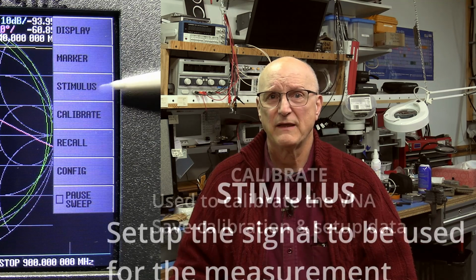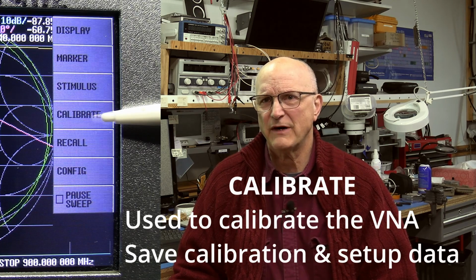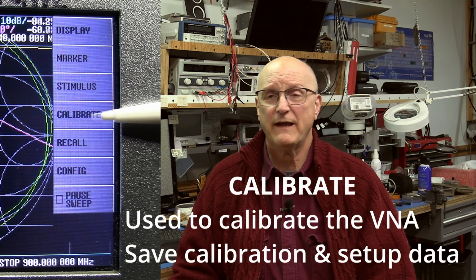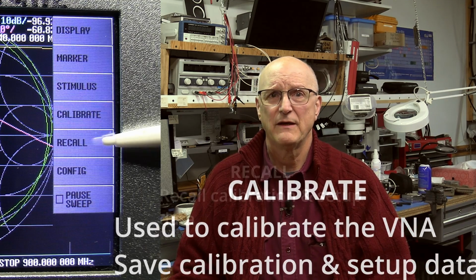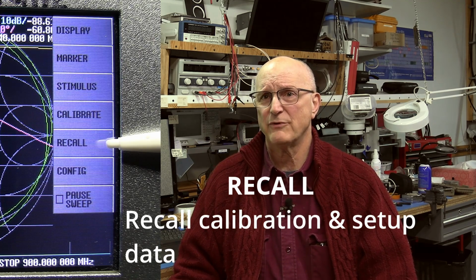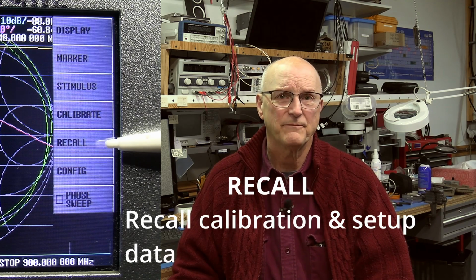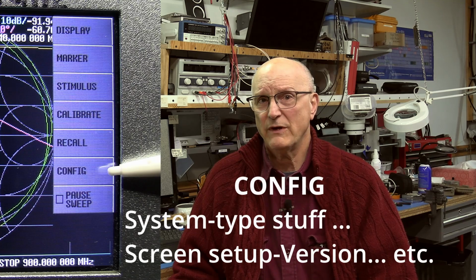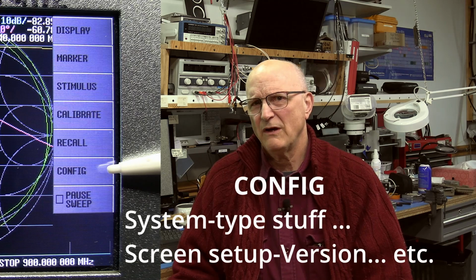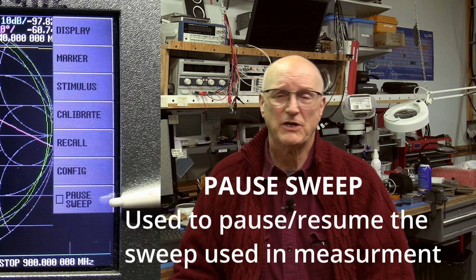Stimulus is where we go to set up the various aspects of the signal that the nanoVNA uses in its measurement. Calibrate is where we go through the calibration process to prepare to make a measurement. It is also where we go to save calibration and set up data. Recall is where we go to use previously saved calibration and configuration data to set up our measurement environment. And Config is where we go to calibrate the touchscreen, see what version we're working with, and other system level operations.